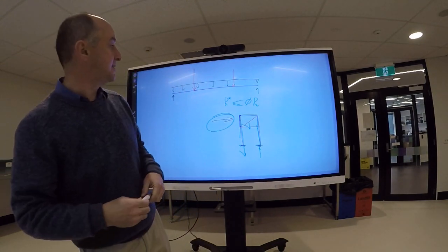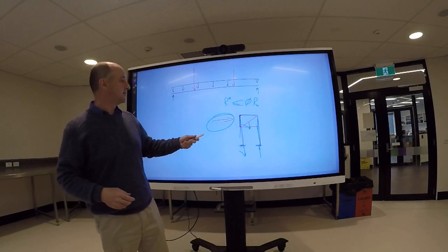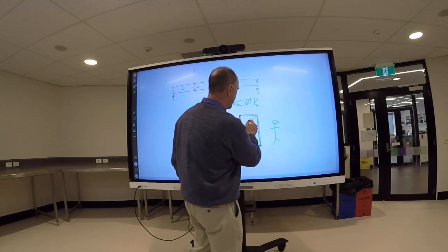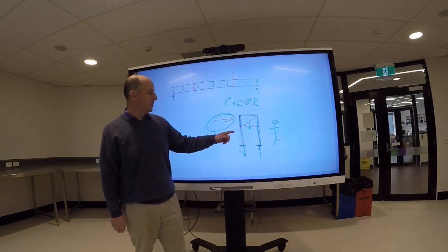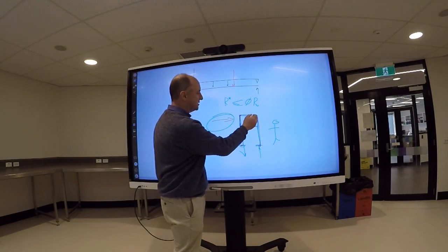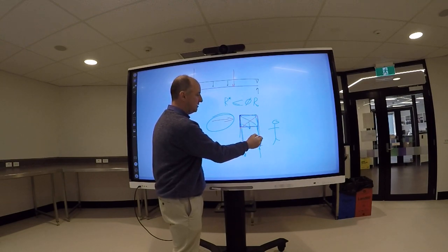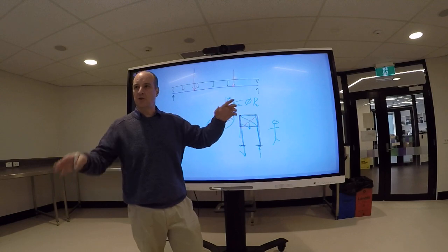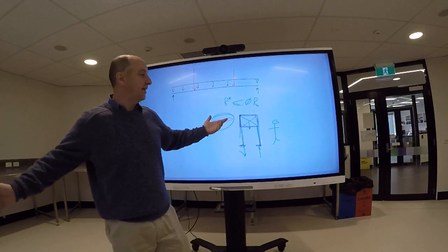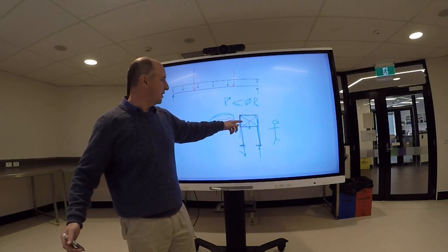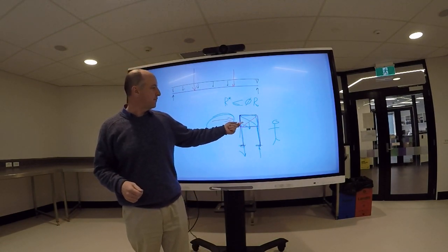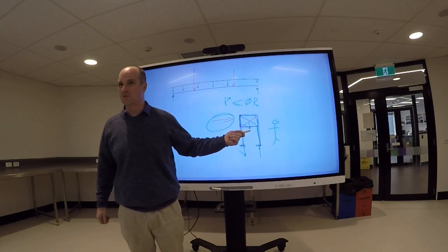There was one, I was coming back to the idiot load. Okay. Let's say you had a structure which was this big, okay, and it happened to be a sign board, and you need to design that to be strong enough. All right. When you design, and that's a solid piece of sign, okay, and there are two legs there. When you look at the loads on that, the wind load on a sign maybe the size of this TV is not actually that big, because it's not very big, right? And other loads on it, the earthquake is pretty insignificant, and you can design your post there. There's no live load on that from people because no one climbs it or is walking on it, so that doesn't really apply.